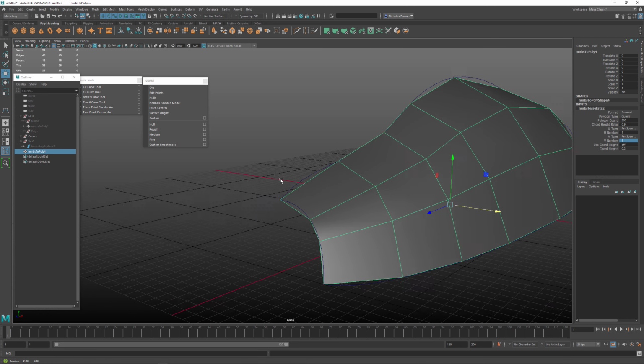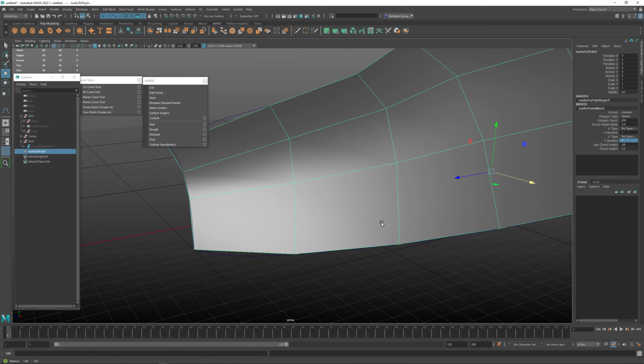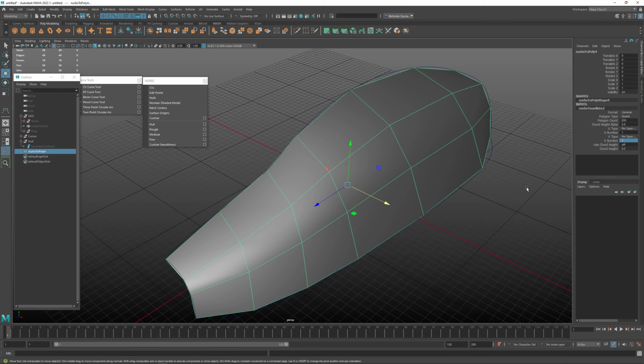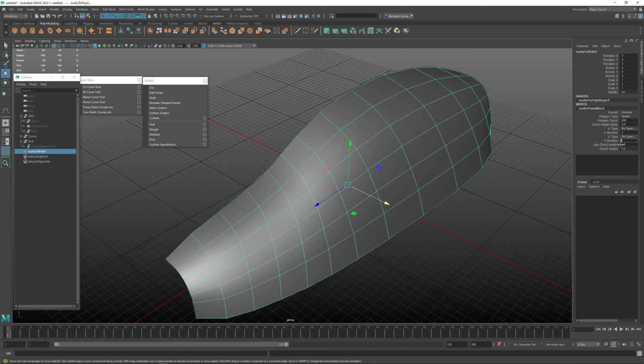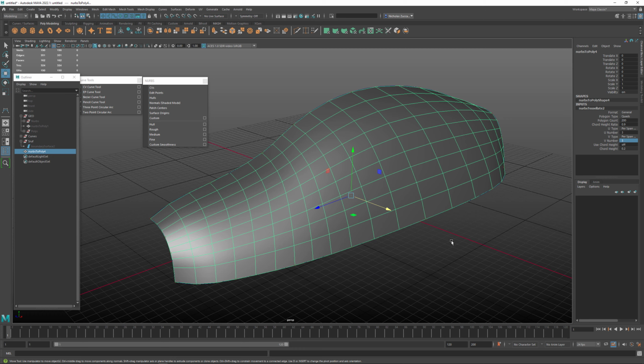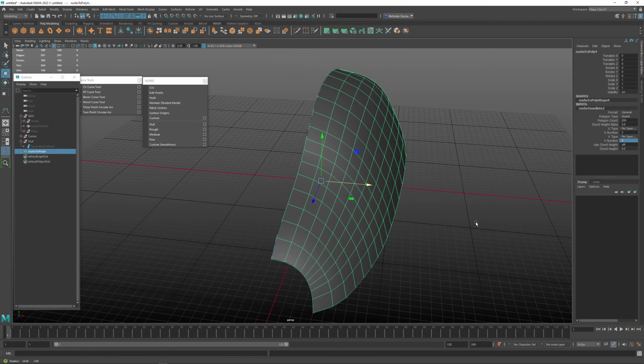This is where it becomes a little bit interesting. This is actually creating geometry on each one of these edit points like this, right? So it's almost like our base cage for our polygon modeling. But then if we wanted to up this, if we do 2 and then 2, this is almost like doing a subdivision level like what we did before. And then if we do 3 and 3, that's really close to taking a base cage and then doing the smooth mesh preview version on it. So it's like you're doing that directly with the NURBS surfaces.